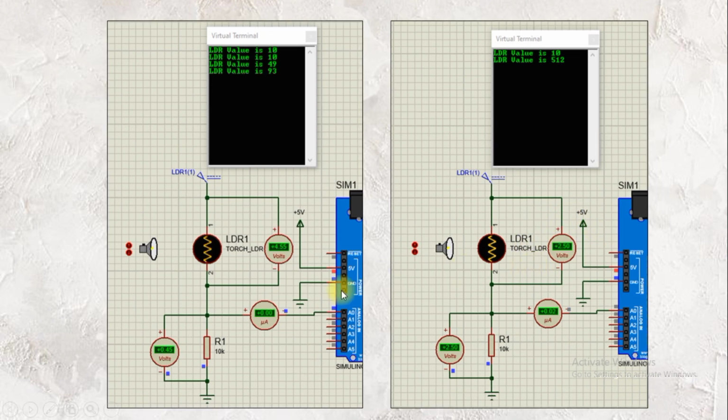For the second, the value is still increasing but still below 100. So even though the LDR detects that the light is increasing, at this condition our smart street lighting will still be turned on, as long as it meets both requirements for LDR and also PIR.